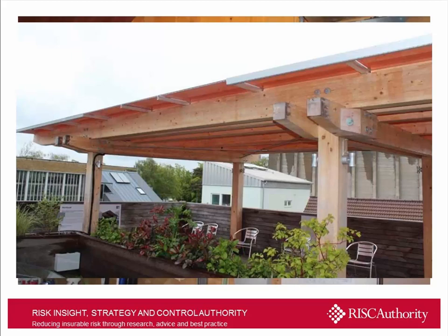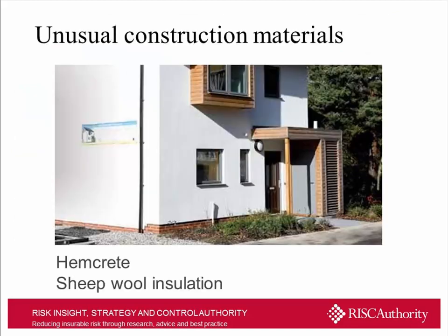But the concerns that are raised with regard to the potential for impacts inside the building itself also need to be addressed, because in installing these sorts of systems you need different ways of controlling it. There is also the potential for far more significant penetrations of compartmentation lines, which again in themselves will need fire stopping. And so there are additional considerations and concerns associated with the use of more modern ways of heating and cooling our buildings nowadays, which need to be considered.